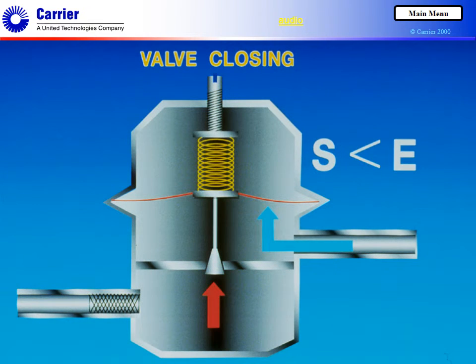If the evaporator pressure rises above 69 psig, the evaporator pressure overcomes the spring pressure. This bends the diaphragm upward and closes the needle valve. Refrigerant flow to the evaporator decreases, and less of its surface is flooded. Less refrigerant gas is evaporated, and the evaporator pressure returns to 69 psig. This action brings the spring and evaporator pressures back into balance.